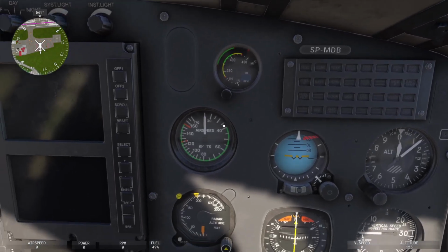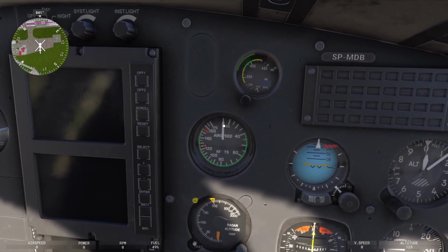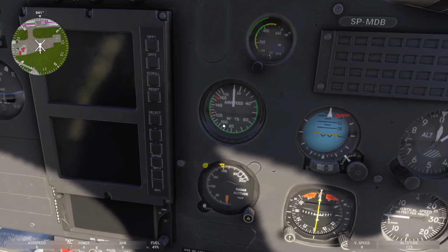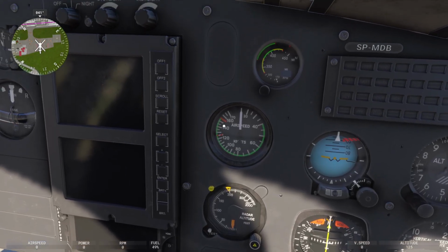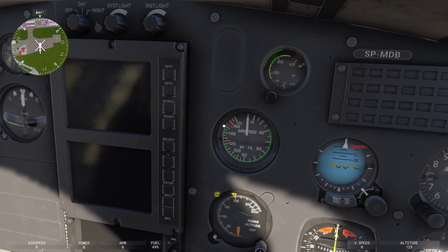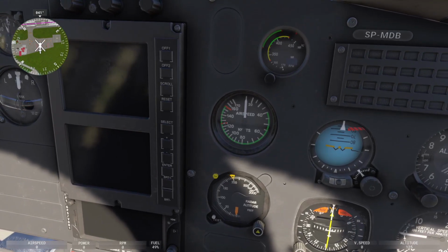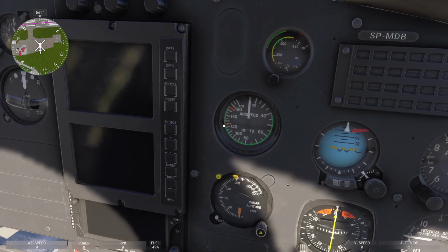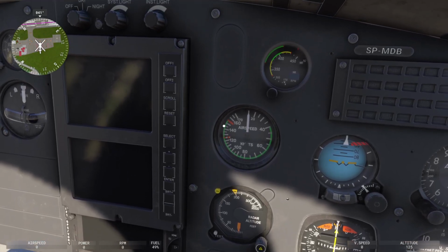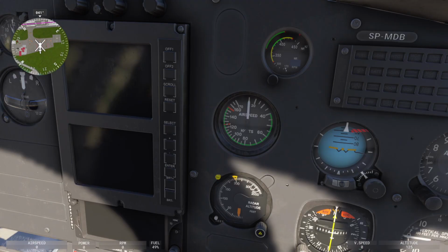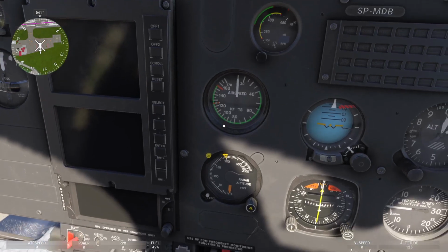We can see. Your airspeed indicator is here. This is your airspeed in knots, with this aircraft having a maximum of just under 156 knots. Okay, you'll see the checkered flag here. You don't really want to be flying over that. You don't really want to go past that. Okay, so we'll try and keep it around 120 knots when we're flying.